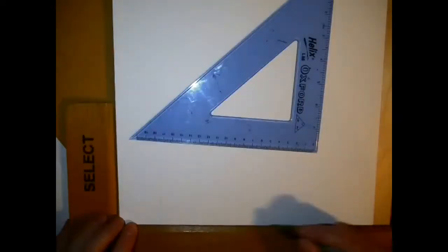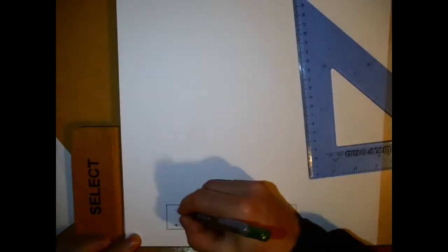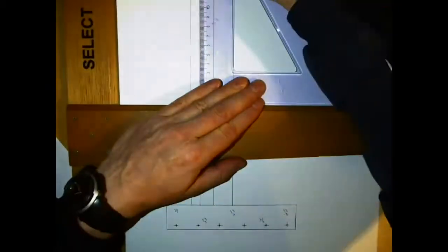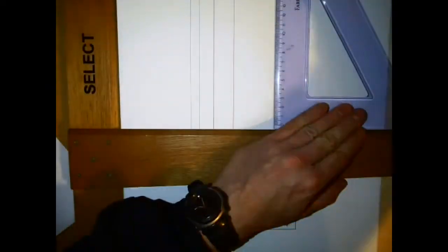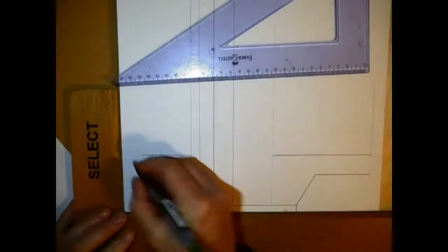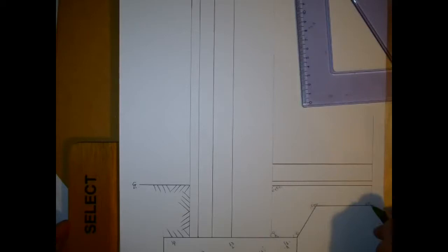So starting off, I'm going to start by drawing the foundation, and I'm putting a few sizes in here. The important sizes I'm putting in, because it's an external wall, I'm putting in the 300 millimeters from the edge, 100 millimeter block, 150 millimeter cavity, and a 225 millimeter block on its flat. And then I will extend 450 millimeters out for the flue gathering, and that's the sizes that we have here. So 100, 150, 225 and 450 for those lines coming up from where the foundation is, and extended 300 millimeters around that there to accommodate for the extra sizing.